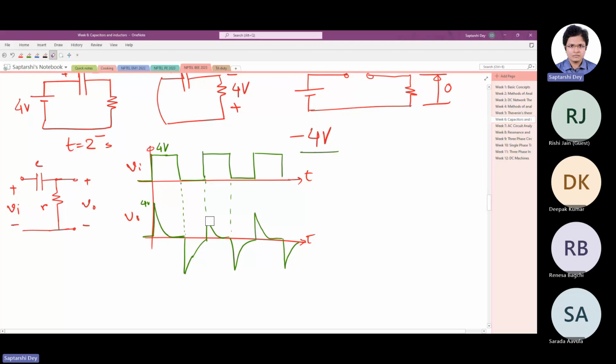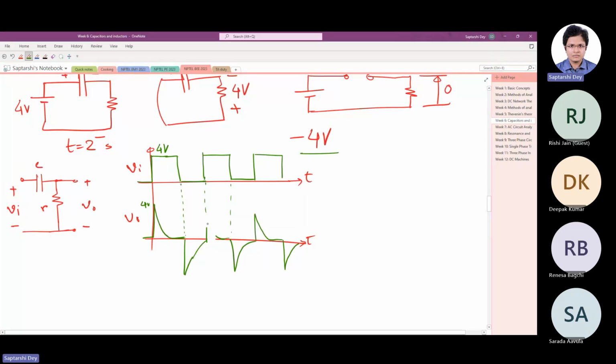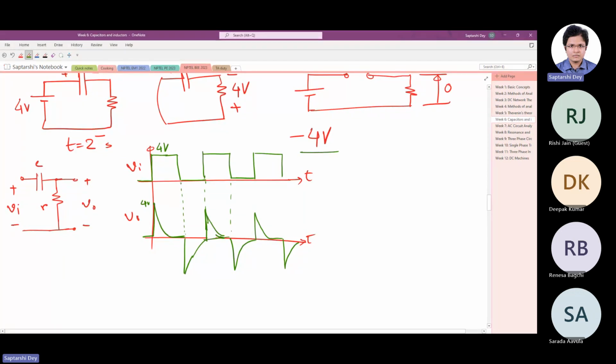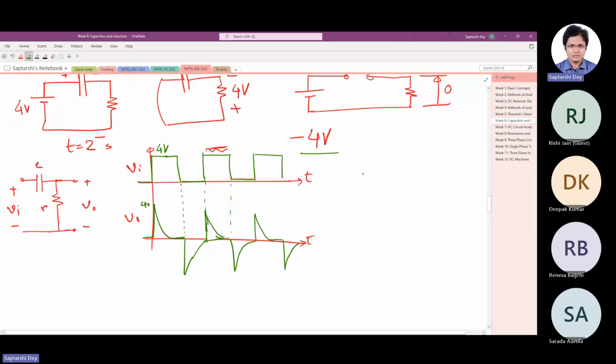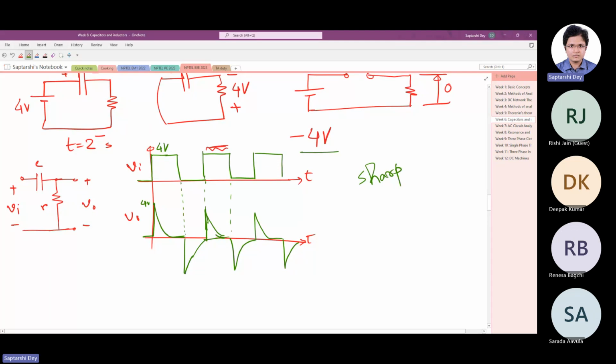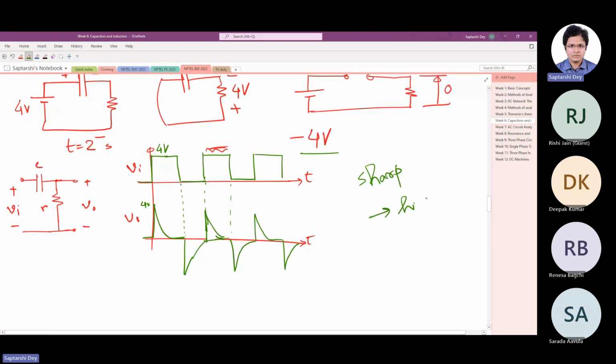So you see what is happening here. What you gave, this will be more clear to you once you study Fourier series and all in your higher classes. But say this square wave, if you look at the flat portion of the square wave, this area, this represents the low frequency component of the wave. Whereas this transition, very sharp transition, always keep this in mind. If there is a sharp or sudden transition, that means it has a high frequency component in it, for sure.